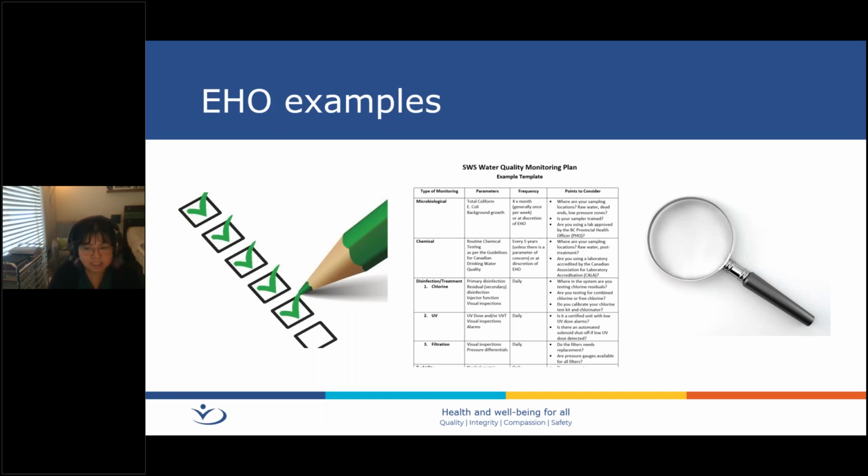Check the water intake for any signs of damage, check the treatment system to ensure it is functioning properly, check the turbidity or water clarity data, pressure within the distribution system, check the residual and the chlorine residual and chlorine demand. So in this situation, the water supplier can also compare the information to records, any maintenance logs that are available to see if there are any anomalies.